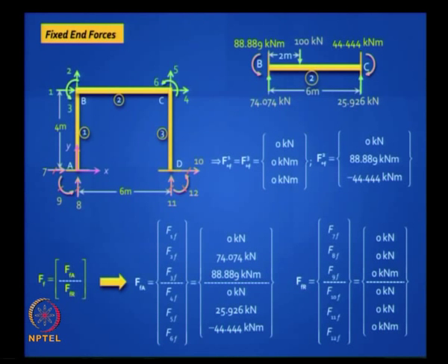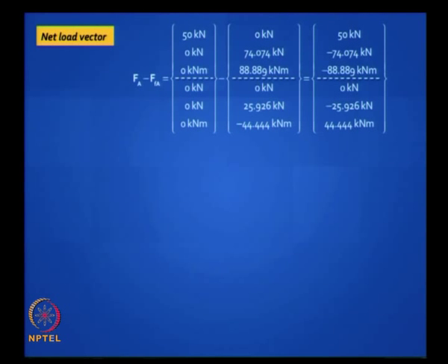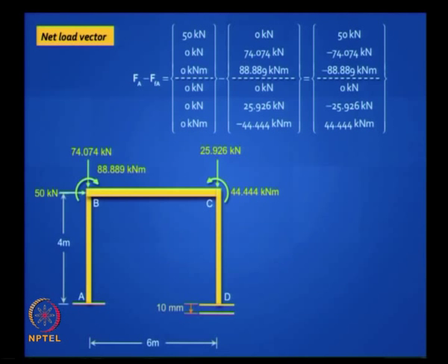Okay. What is the next step? No, we still need resultant loads, which is actually the same as this, because you have a 50 kilonewton acting at the third coordinate. So you do this, then you draw a sketch and you say, now this is a structure that I am going to analyze and superpose this result with the friction force values that I get. This structure is loaded with equivalent joint loads, and this is identical to my original structure.